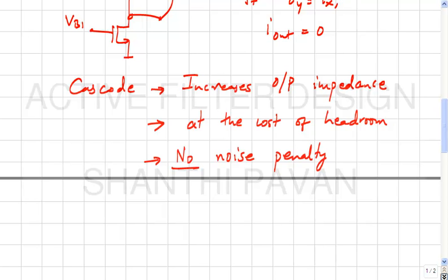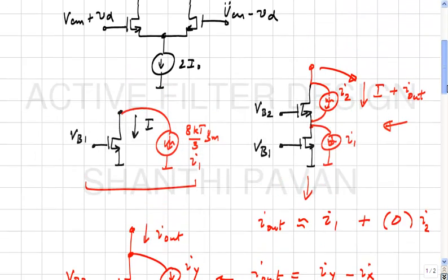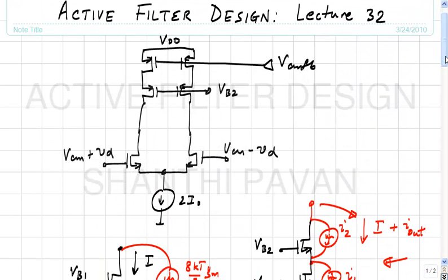All right. So this finally is our complete transconductor with whatever improvements we've deemed to be possible. I am not going to draw here the common mode feedback circuit, which you have seen quite extensively. Another thing to bear in mind is that this VB2 and all that will not be available from outside. You have to generate it yourself. And how do you think you'll be able to generate VB2?